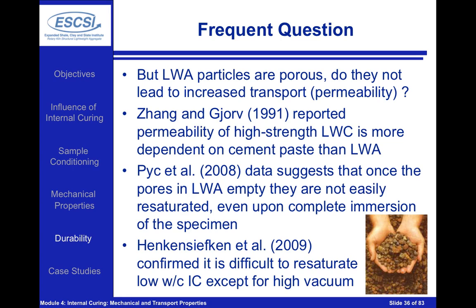The whole idea behind this is that the lightweight aggregates themselves will actually empty out of water, and it's very difficult to resaturate them even if the sample is placed back in water. It takes a long time for this to happen. Henkensiefken showed that it's very, very difficult to resaturate a low water to cement ratio internally cured concrete unless you actually use vacuum in the overall system.